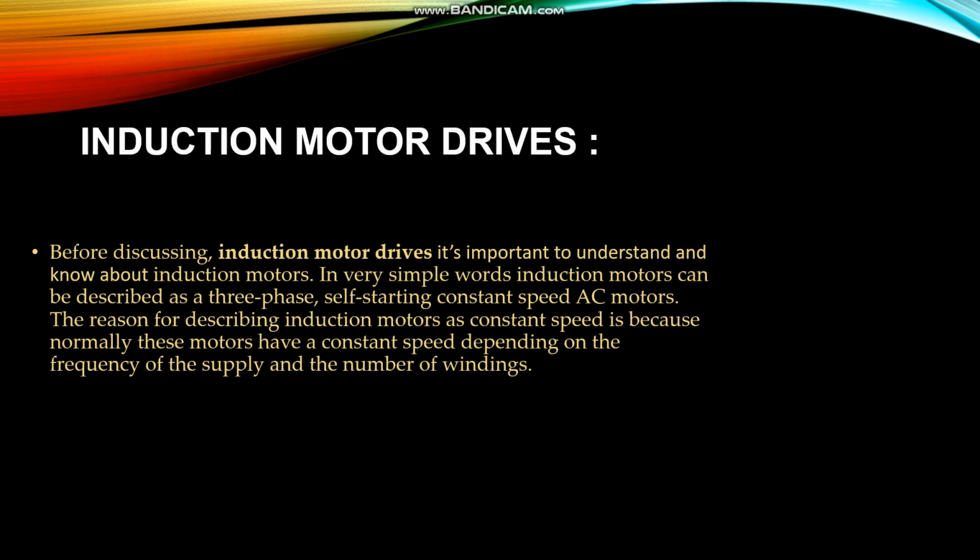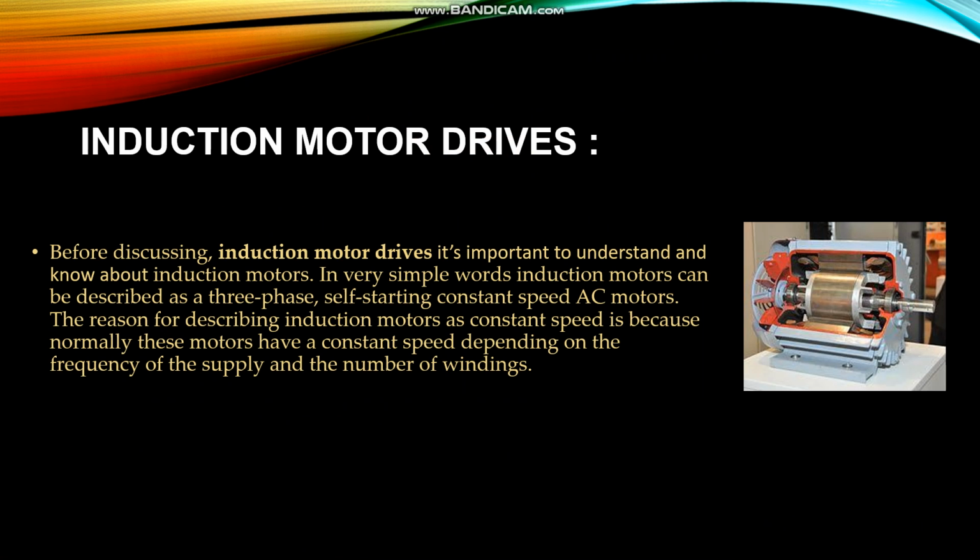Induction motor drives. Before discussing induction motor drives, it is important to understand induction motors. In very simple words, an induction motor can be described as a three-phase self-starting constant speed AC motor. The reason for describing the induction motor as constant speed is that normally these motors have a constant speed depending on the frequency of the supply and the number of windings.